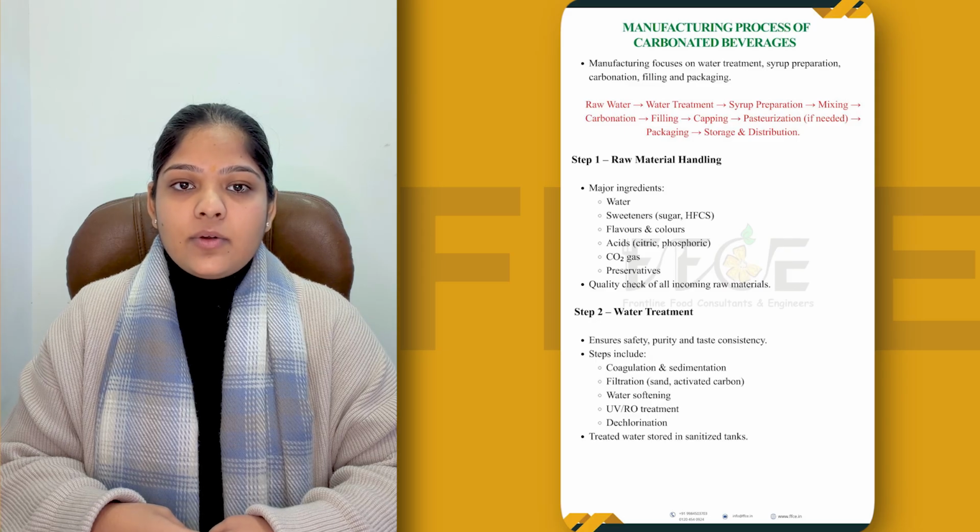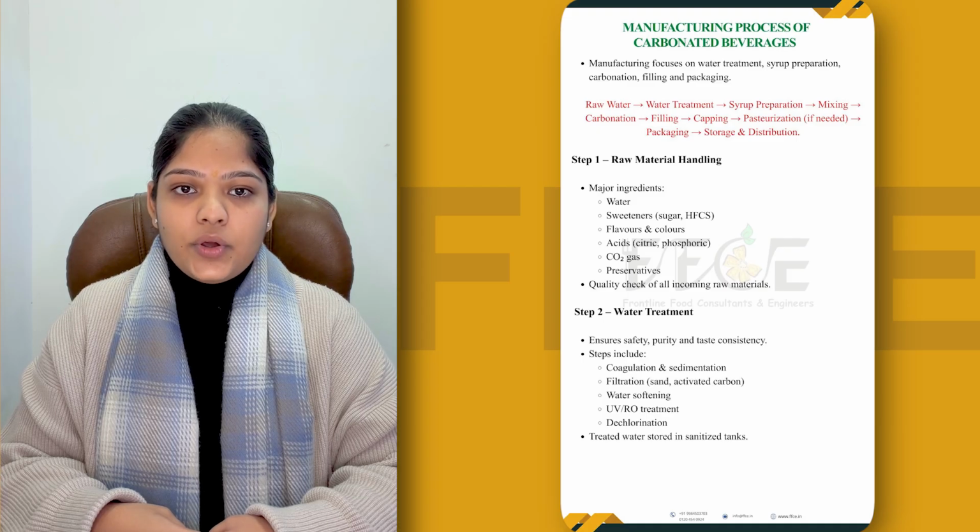So now we'll discuss the second step, which is water treatment. Water treatment ensures safety, purity, and taste consistency. It involves coagulation, filtration, activated carbon treatment, softening, UV or ozone disinfection, and often reverse osmosis. The treated water is stored in sanitized stainless steel tanks to prevent contamination before further processing.